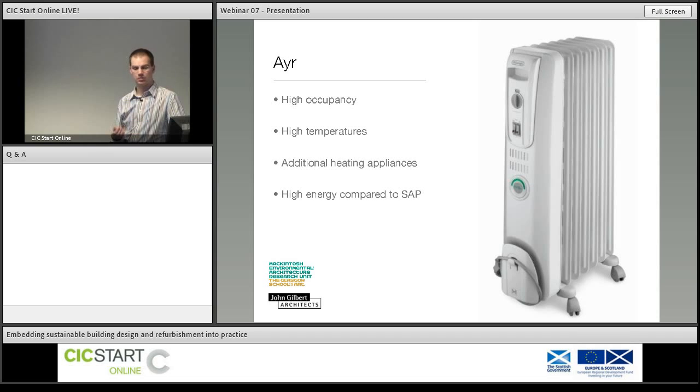The occupants said that they turned it off because it caused drafts, and they didn't use mechanical ventilation at all. So that's an interesting bit of feedback, particularly at a time when the building regulations are really starting to push a lot of people towards mechanical ventilation and heat recovery. I think the thing that comes from that is looking at how that's implemented and the controls available to people. If there's only an on and off, then people may well turn it off. If there's more control over that ventilation, then that might mean that it's still kept on.